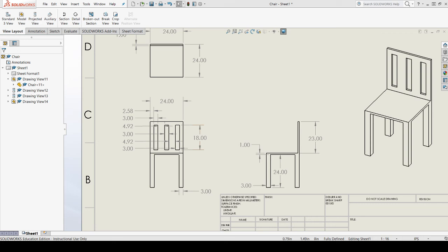There's a lot of different fit sizes, for example. There is a loose fit, which is something that fits in loosely, or a free fit, or a medium fit, or a transitional fit, or an interference fit. A loose fit just kind of goes. An interference fit is like, you need to take a ton of pressure to actually fit these parts together.